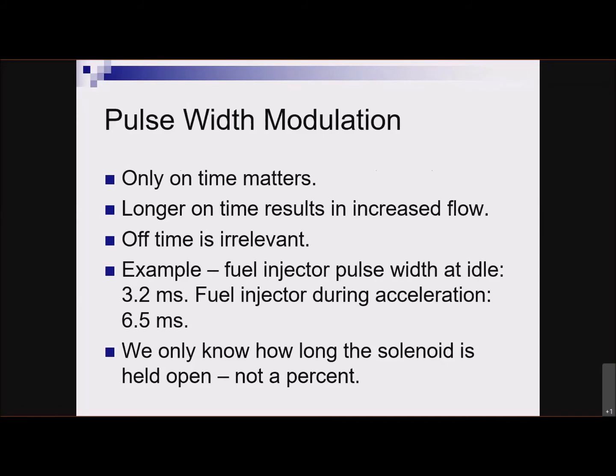The solenoid that controls line pressure may very well be pulse width modulated. Your daytime running lights, so they're your headlights, but they're on only half brightness or less. The current running through that may be limited by pulse width modulation. So it's sending little pulses of current instead of just turning it on and leaving it on steady. To make it brighter, they lengthen the pulses. With the pressure solenoid, to up the pressure, open the solenoid more, they lengthen the pulses.